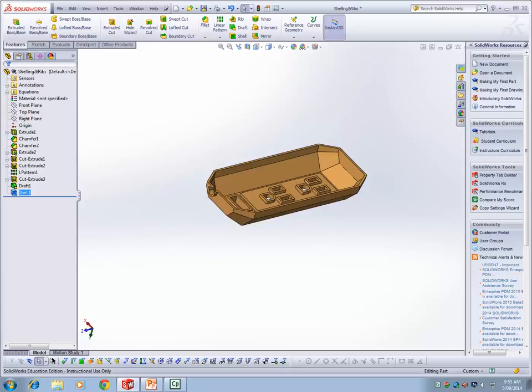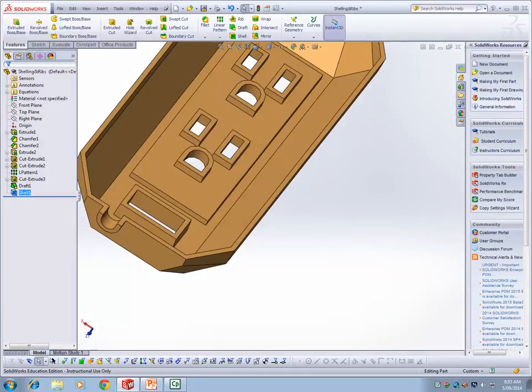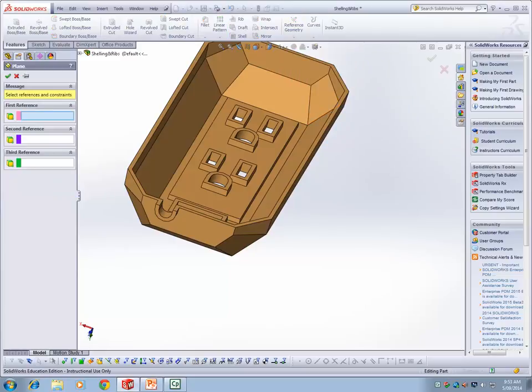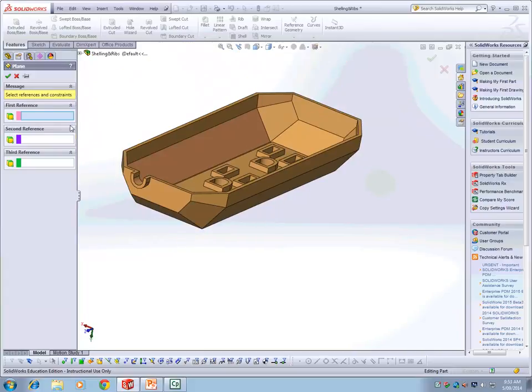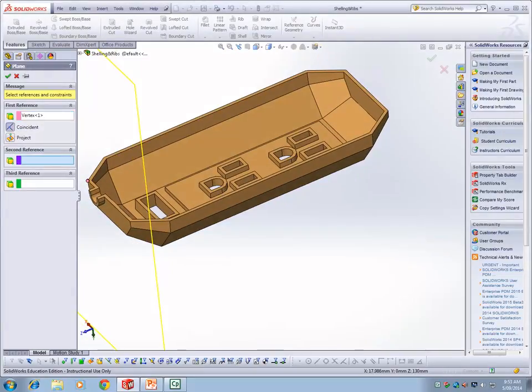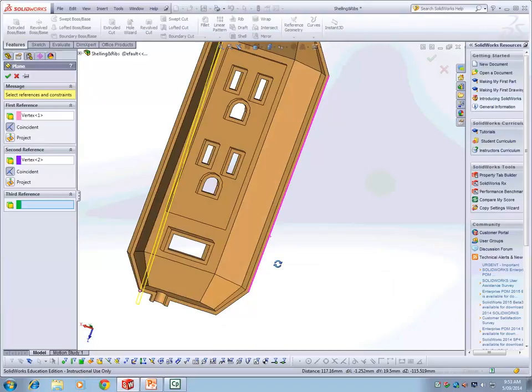Once this is done, I'll quickly show you how you can add planes using a geometry plane. So for your normal plane, you need to have at least 3 references. Say if you are using 3 vertex points, so in this case I can select a vertex point, say here. It won't draw a plane, please, it will just draw a line, or an axis points.